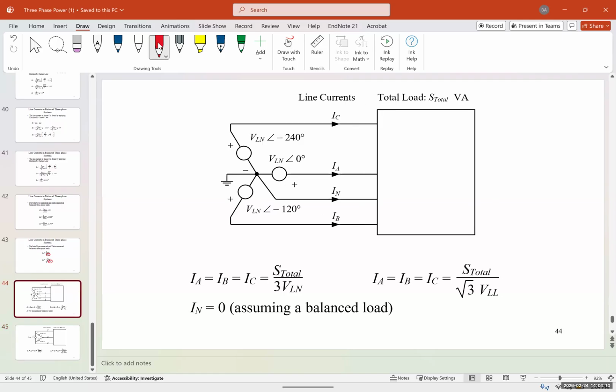Why? So the interesting part is one of them has a higher torque, the other one has a higher power. We always start with a Y connection and then we switch to delta. So even if we have a three-phase delta motor, we usually start it in Y, and I'll explain this in